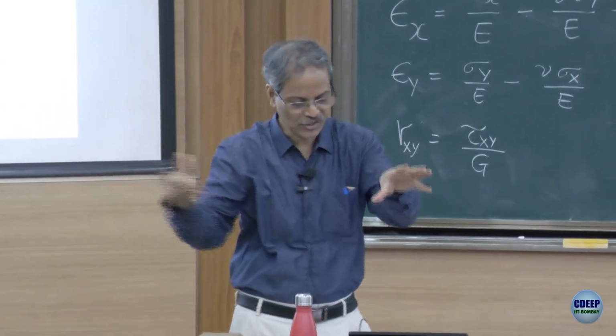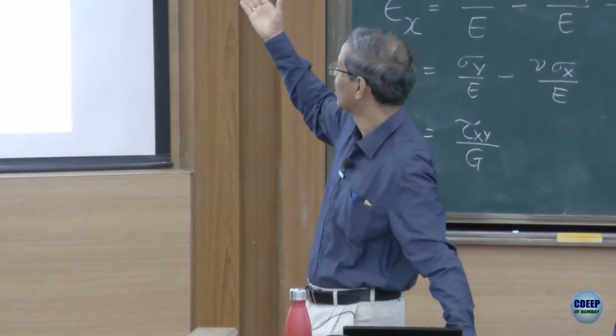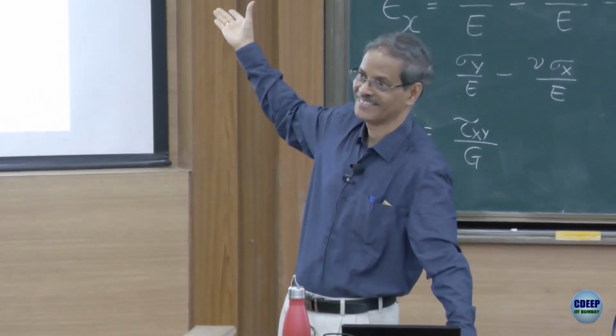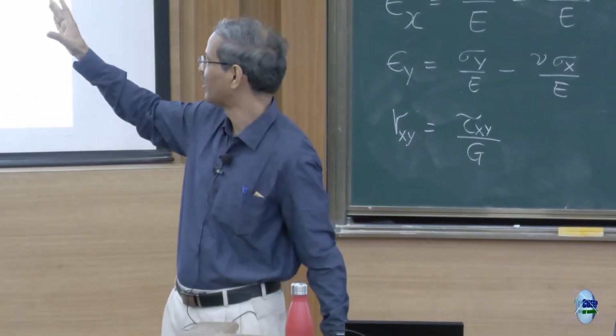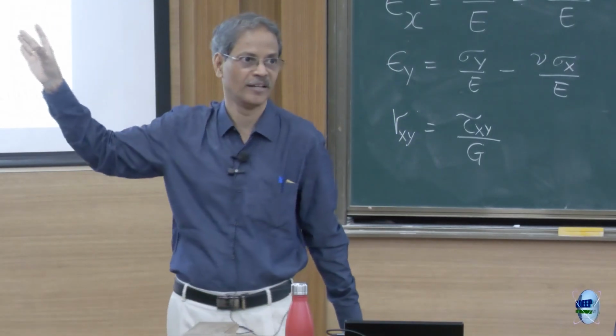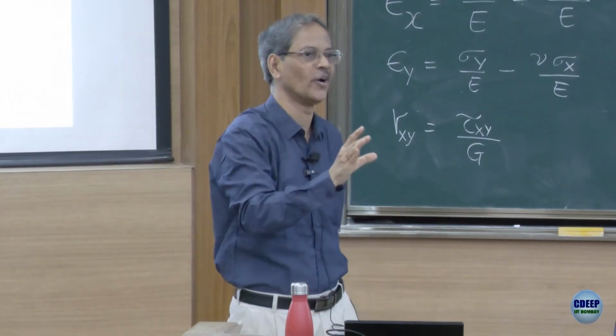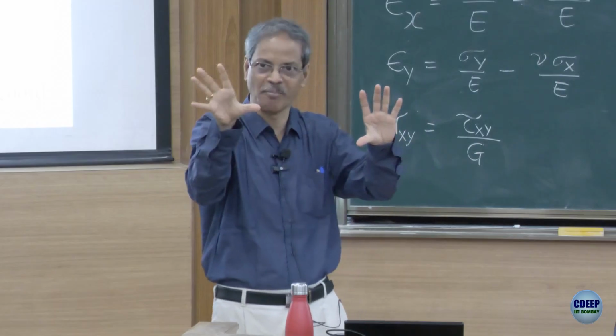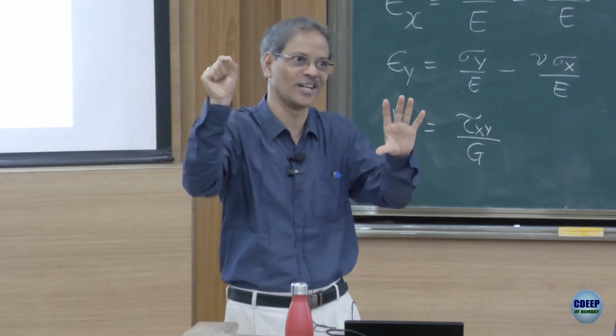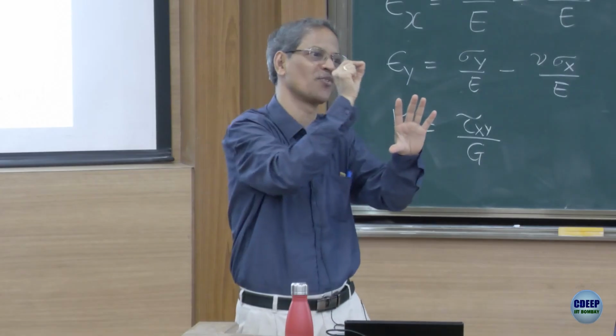The shape of this could be a general quadrilateral in the xy plane. But in my formulation, using the mathematical structure I just now coined, it would be a square. So that quadrilateral is mapped, every single point in that quadrilateral is mapped into this square.